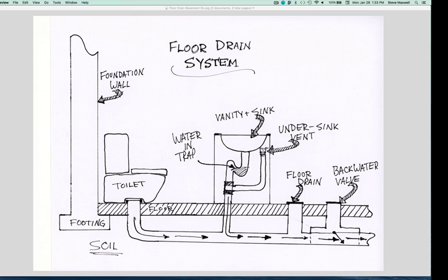Just because it's creating a vacuum. The water's creating a vacuum as it moves down along the pipe. And let's just say that vacuum continues past the point where a sink or shower might connect to that system. Well, the suction is going to want to draw all the water out of the trap because it's sucking on these pipes as the water travels down.